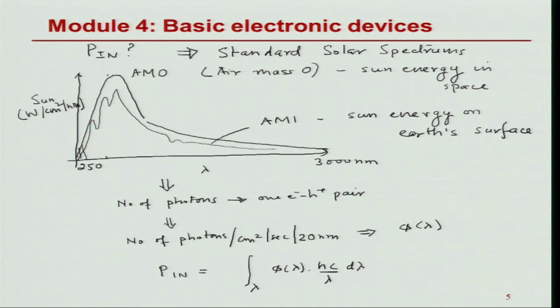So what we are characterizing in a solar cell is how much power I am collecting from the solar cell and how much total sun power, at that point, I am able to collect per unit area. If I take that number, that is the efficiency. Now this is the number that we quote again and again when we describe our solar cell. Keep in mind, whenever we quote this number, we must also quote the standard spectrum we are using for doing this measurement.